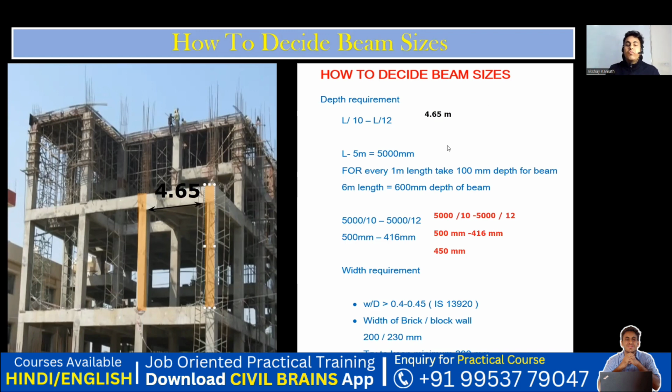It's very simple. 4.65 m, I'll take it as 4650 mm. 4650 divided by 10, I'm getting 465. And again 4650 divided by 12, I'm getting 387 mm. So 387 mm and this is 465 mm. Now you're free to choose any size. Your value should lie between 387 and 465.